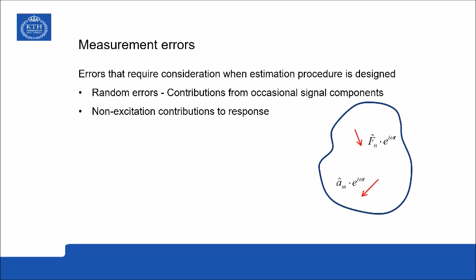What we want to measure is actually the response acceleration caused by this exciting force, Fm. All other forces that happen to excite the system and contribute to the measured response are unwanted. So we somehow must be able to eliminate or reduce the influence of these unwanted excitations.